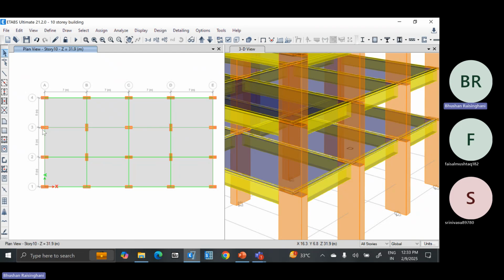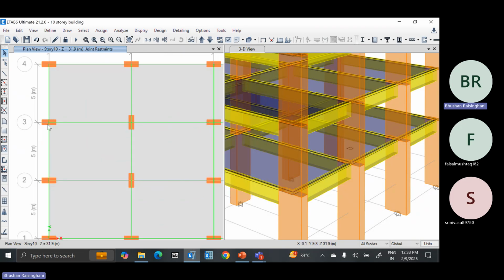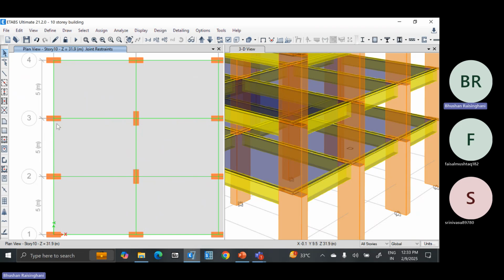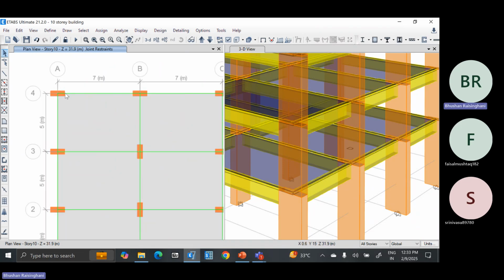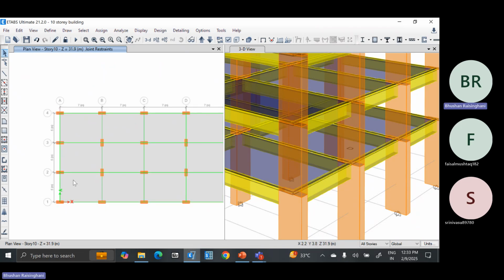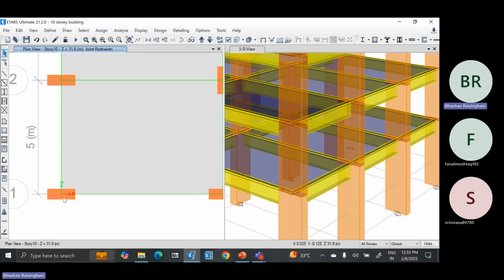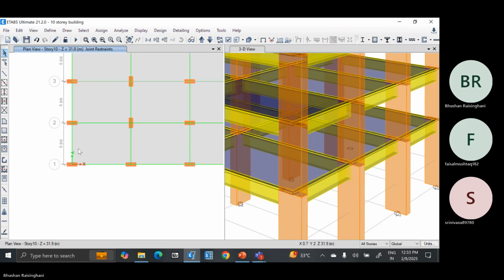It is generated. Generally, the columns never project outside the building like this. So it is preferred to have these rotated in these directions. This column, if it is in this direction, then it will be shifted inside as an offset. So that offsetting you have to give. So the face has to be straight. All these things will happen once you model a real building, in which these columns that I have shown as projecting outside will not happen. So the face of the beam and the face of the column will meet at the perimeter. So that much offset has to be given to each column, right?